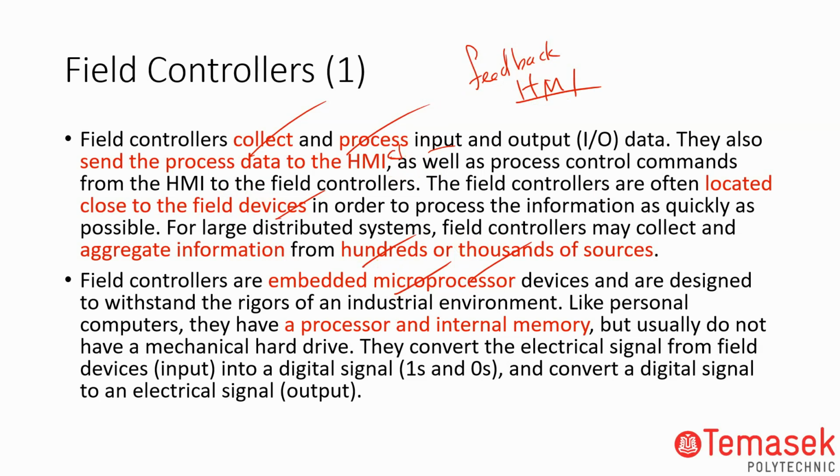Is there a difference between an industry one and a normal one? Practically, it can take higher temperatures, that's all. But if you really ask me, is there a real difference? There's no real difference. The components inside a controller and a PC are the same, because they are identical for cost saving and so on. The key thing is, you may say, I have a DSP within my controller.